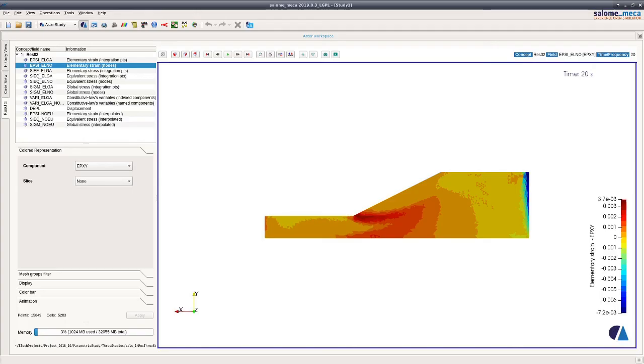Now coming back to our strain direction here, you see in this portion the strain is positive because my material is coming downward, okay, and on the y plane the direction is clockwise, right? Clockwise rotation kind of thing. Similarly here there is a slippage in this portion, and this is my negative. So as a reaction, this portion of the soil will be trying to rotate in anti-clockwise direction, okay, and therefore it is negative. So that's how shear strain directions can be interpreted.